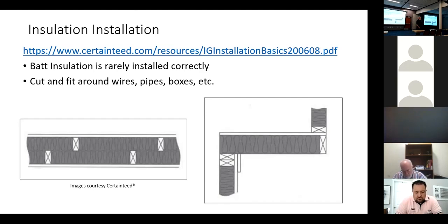I put 1.5 inches of polyiso on the outside of my house, and I'm sure it's decayed a little bit, but it's still continuous insulation. It made a huge difference. The thermal images show the studs starting to disappear. It's an incredible product. The extruded polystyrenes and such, not so much.